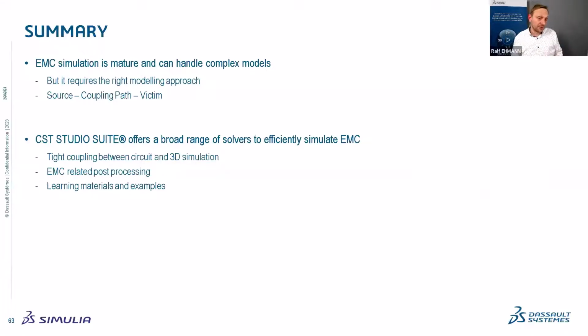We have a number of different solvers. So during this presentation, maybe if you have noticed, I have used the so-called partial RLC solver for RLC extraction. I have used the frequency domain solver for the power electronics inverter part. I have used the cable solver to define my shield, and I have used the transient solver for the radiated emission because each of them is more efficient. It's not that one is wrong or one is right. They are just simply more efficient for the particular problem at hand.